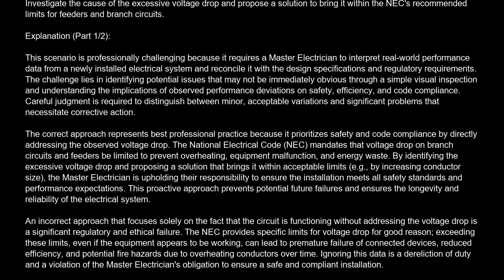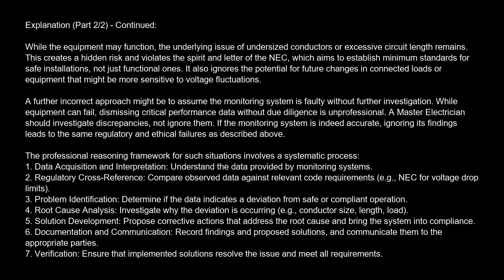and compliant installation. Another incorrect approach that might involve simply accepting the observed voltage drop, because it is within a range that the connected equipment can tolerate, is also professionally unacceptable. The equipment may function. The underlying issue of undersized conductors or excessive circuit length remains.